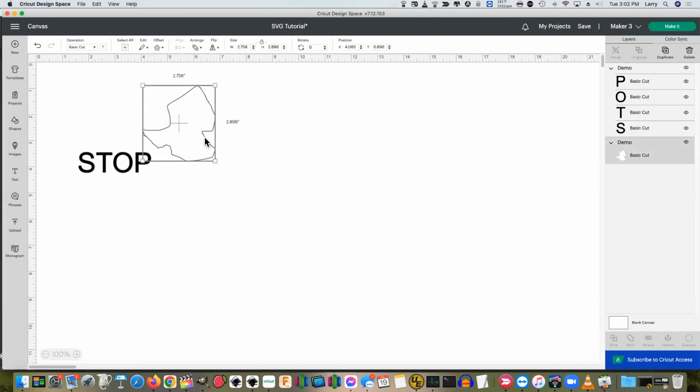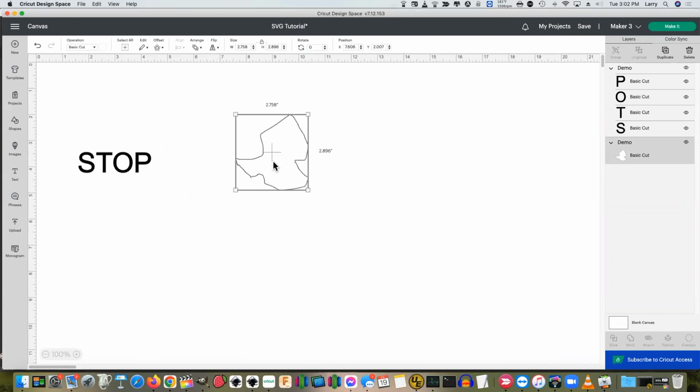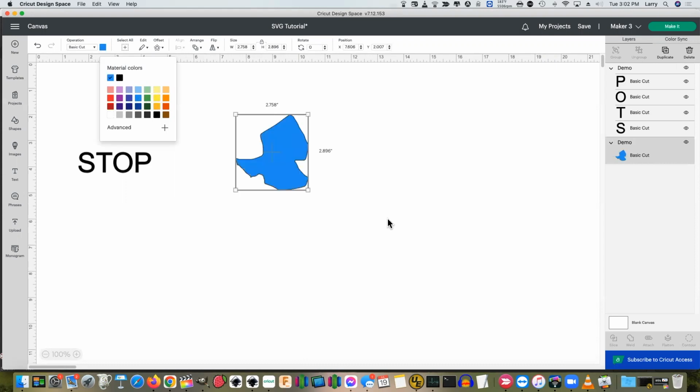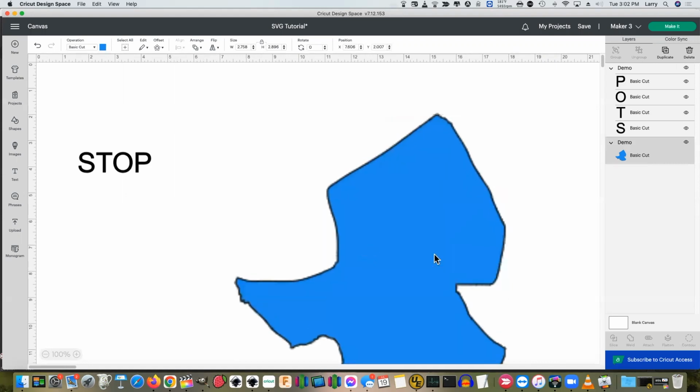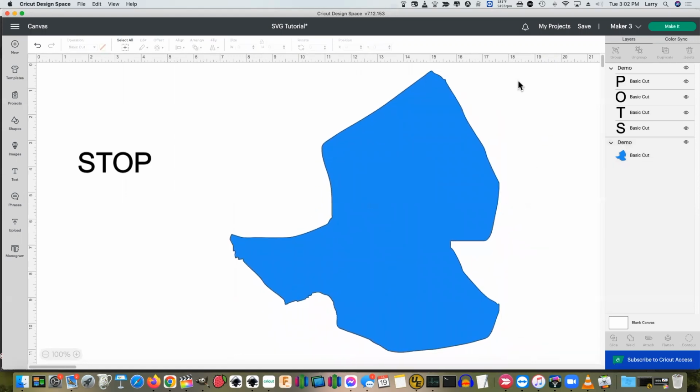Now this next one is an image that has got a white background. It's got a white color to it. Because Inkscape uses background white colors, it thinks that white colors are backgrounds. We need to change that color. So I'm going to come up to the color, and you can change it to any color you like, just so that it is not white. Okay, and then we can go ahead and make that one large. Go up and do crosshair snapshot again.